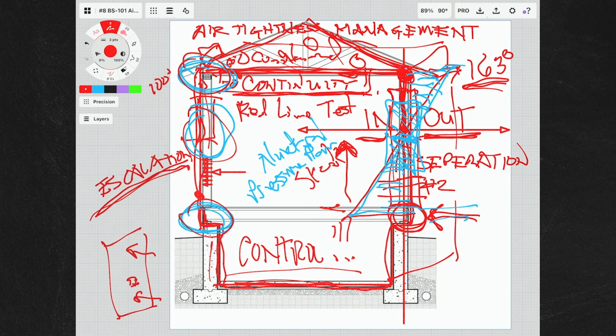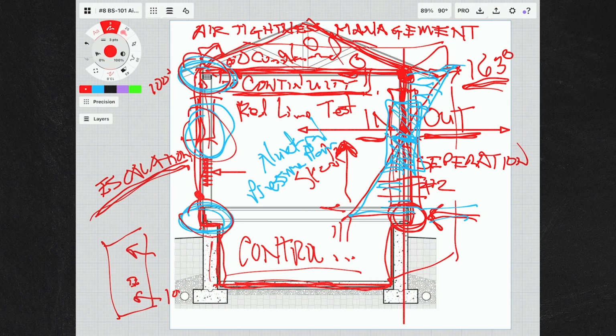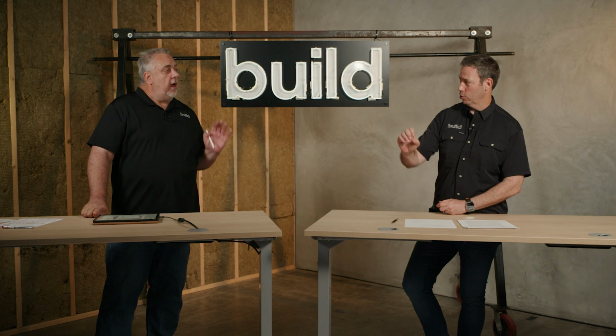And it's something like diffusion, moisture migrating through a material. It might be 1 cup of water. You cut a hole 1-inch square, and it's an order of magnitude. You get 100 cups of water that can move through that 1-inch square. Because of the air. It gets on the air train, right? So that moisture jumps on the air train.